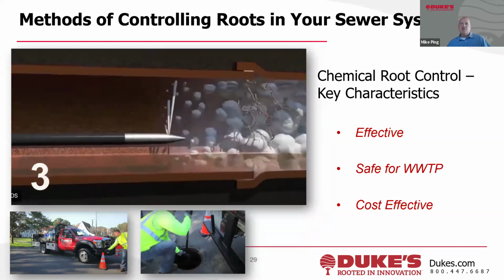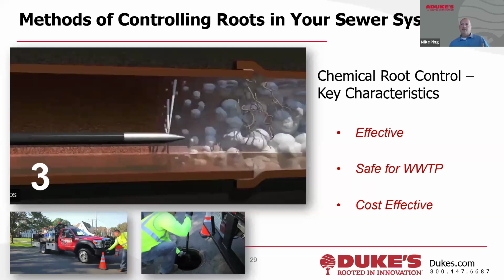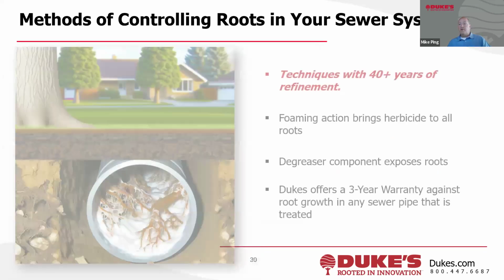The pumping system is turned on, applies the product, and it pulls back at a rate of 1 to 2 feet per second. The consistency of the product is very much like a shaving cream type consistency, and it fills up as it comes back. If there are any laterals, it may go up the lateral 4 or 6 feet or something on that order, and that's how it's applied. So it's pretty quick and easy.